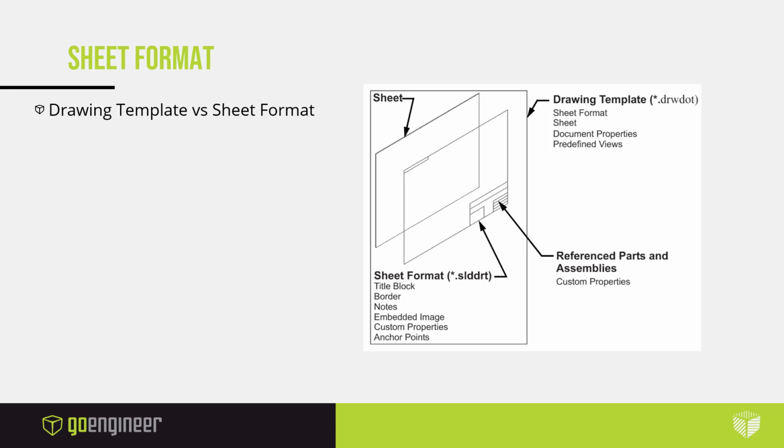If you're not familiar with anchor points, those are very useful in bringing in your bill of material, your revision block, revision table, so that you don't have to place them and align them. You can just click and add them, and they're added to the title block.